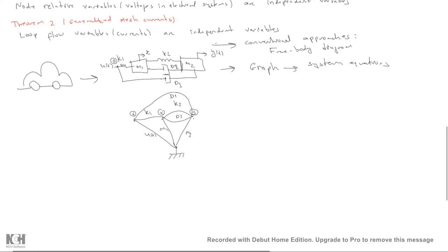Let's write it here: the sum of all the generalized admittances attached to a generic node I, for all k, where we are writing the node equation for node I, minus, between this node I and all the other nodes, if we have any components, we sum them.